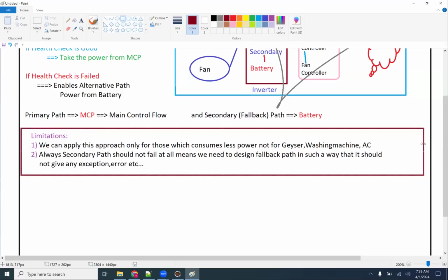So the first limitation, I'm okay. Second limitation, I'll make sure that I take a battery which is tall tubular in design, has a good warranty, and I will use it as per the guidelines the battery companies give, in such a way that it gives long life. Then if these two limitations are there, I can use it.